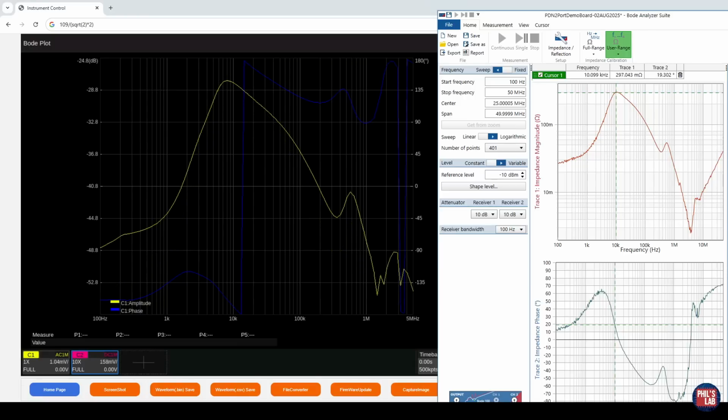And here we now have the measurement finished, and this pretty much has the same shape as our Bode 100 measurement using the vector network analyzer. We are doing essentially the same measurement just in a different way, and we're applying a current load stimulus and measuring the output, and that transfer function V over I is our impedance profile. And we have the same rising characteristic. We're peaking at around 10 kilohertz, afterwards we're dropping off. We have the effects of series and parallel resonances, and also for the multi-layer ceramic capacitors a bit further on.